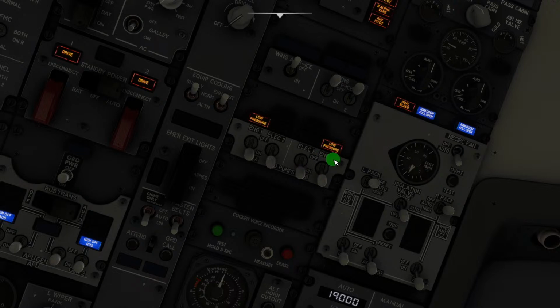What the note is saying is that if you lose the engine one, which is the pump with more capacity, and you have high demand, there is a chance that you will see the low pressure light illuminating for the electrical one as well.